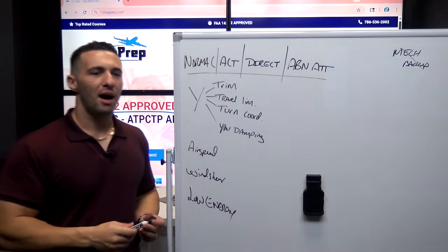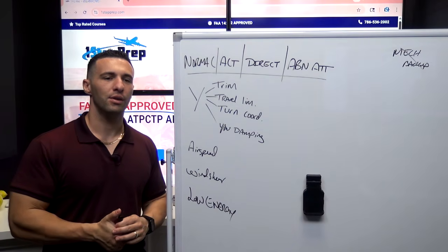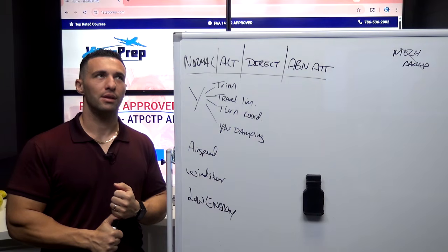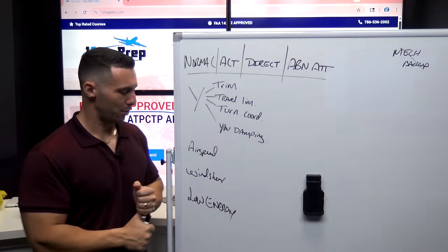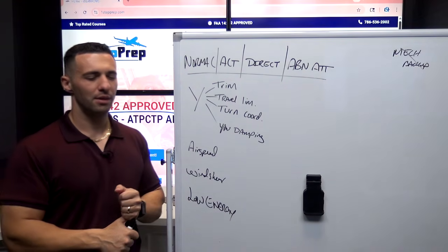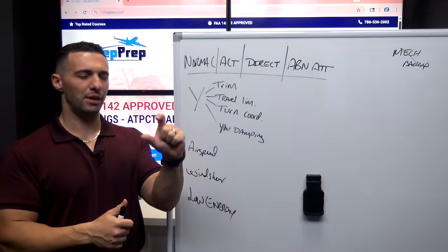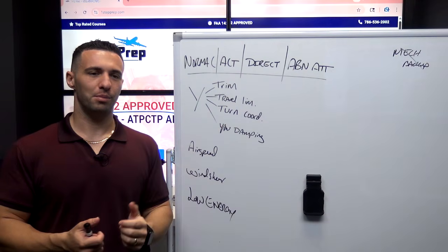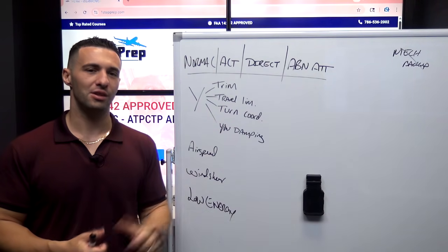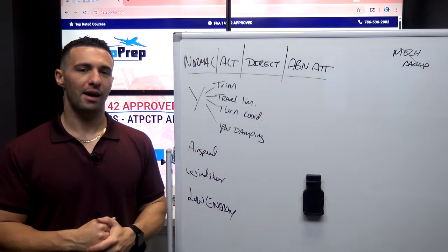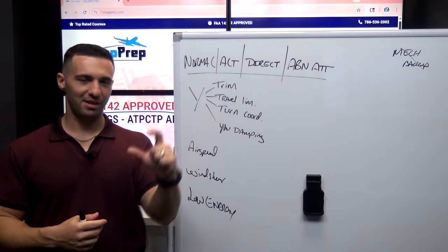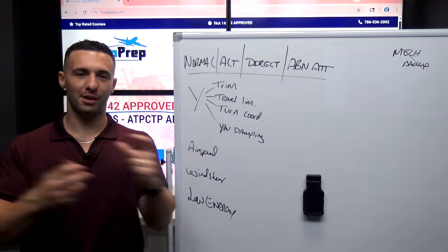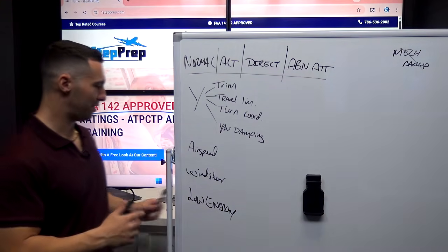Can alpha max speed be higher than high angle of attack speed? If I understand what you're asking, maybe you're saying is it possible for alpha max to activate technically, despite the fact that I'm not even near the airspeed alpha max presentation? Yes is the logical answer, because the speed presentation is only that. It is a presentation. So you could technically have reached alpha max even though the presentation didn't truly catch up with where the AOA actually is. And the activation of the protection is based on the AOA and not the speed. So yes would be the answer. That's what I would say to that.